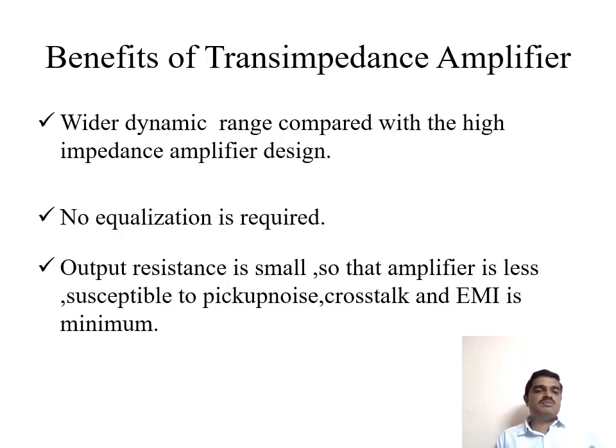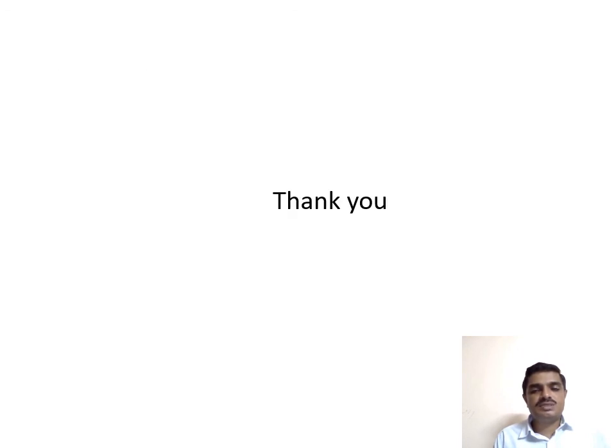Benefits of the transimpedance amplifier: wider dynamic range compared with the high impedance amplifier design. No equalization is required. The output resistance is small, so the amplifier is less susceptible to pickup noise. Crosstalk and EMI are minimum.